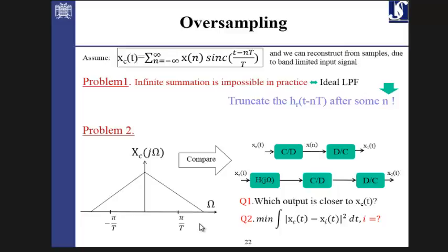So if the signal has more frequency components than what we can sample, which is here, and the symmetric form here, what we do is we put a filter in the beginning to cut the information of the signal, whatever is more than that possible sampling frequency.